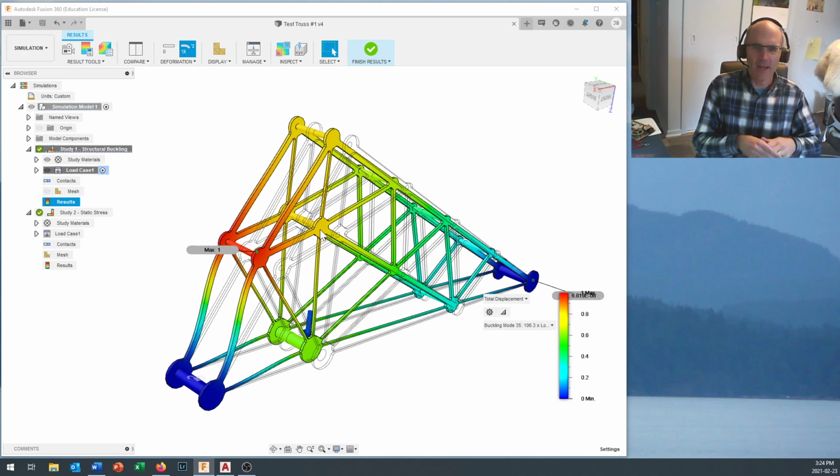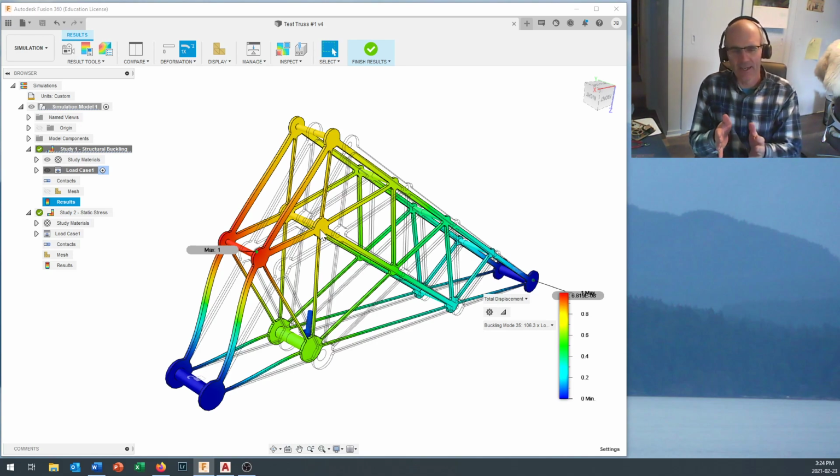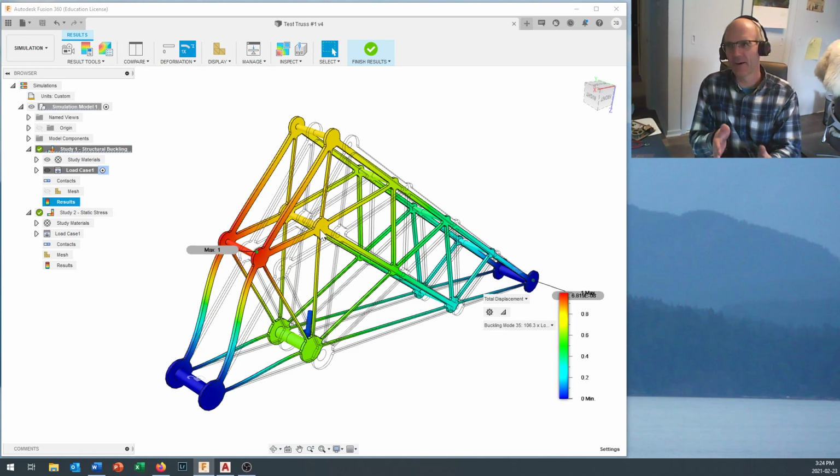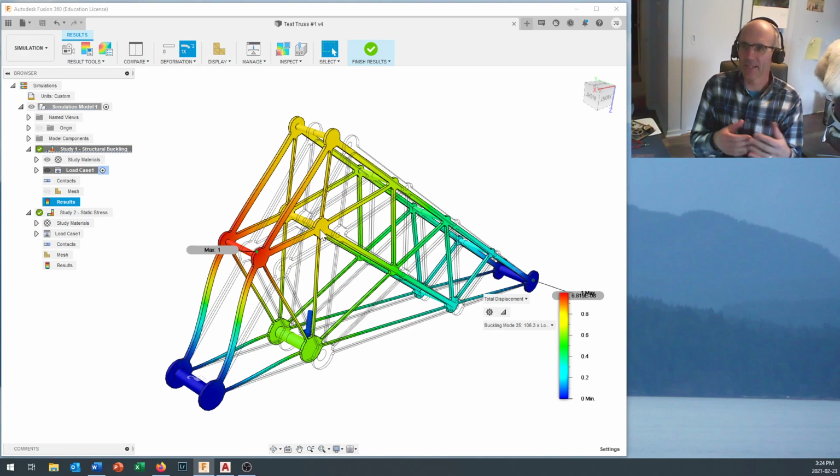Now, this is my video on one workflow for creating this structure. And I chose to use the AutoCAD DXF imported into Fusion 360 workflow because I know the students at BCIT are learning AutoCAD right now, and this is actually a great way to get in and do your offsets, do your trims, do your fillets, and just churn out a cool, useful tool from AutoCAD.